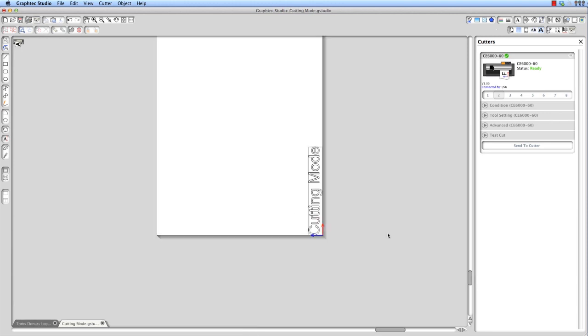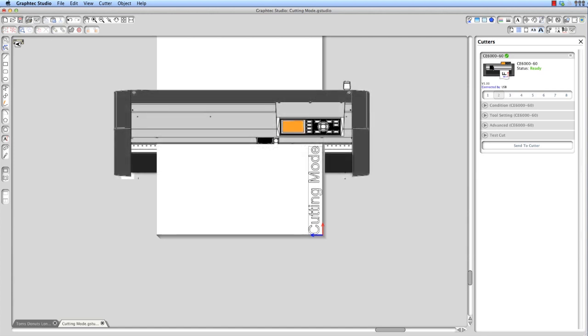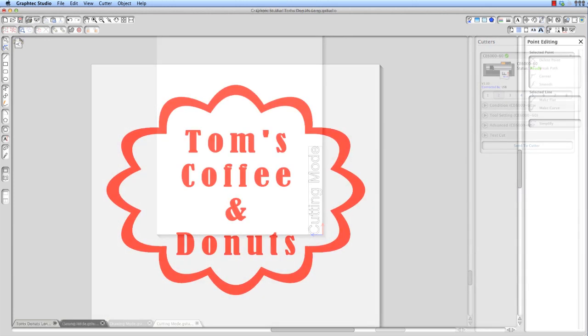graphics. The cutting preview mode is set for previewing the job prior to cutting. The media page becomes a representation of the media to be cut. It generally obtains this from the cutter currently connected at that moment. It will show the orientation of the job design and how it will lay out on the media that is being used or planning to be used in the cutter. When you are in this mode, it is as if your vantage point is looking directly down on the cutter and media. Let's demonstrate this.